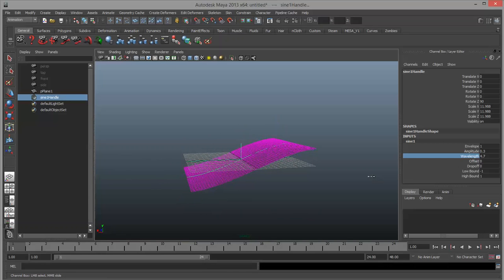Now the cool thing about this is that using offset here will move the wave and cause it to animate and flap. So I like to recommend, for people who don't know how to use cloth, this is a great way to get kind of like a flapping flag or waves in an ocean or something like that. It does have a limit of 10 and -10 for dragging it, but not for animating it and not for typing in the number, so just be aware of that.